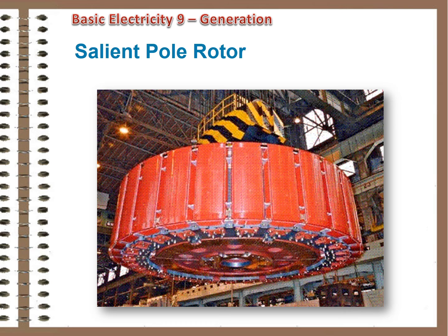This led to the development of salient, or multiple-pole generators. Instead of one north and south in the magnet, like a steam turbine generator, a hydro generator has many poles, as many as necessary to produce the desired frequency based on the optimum rotation speed available from the source.